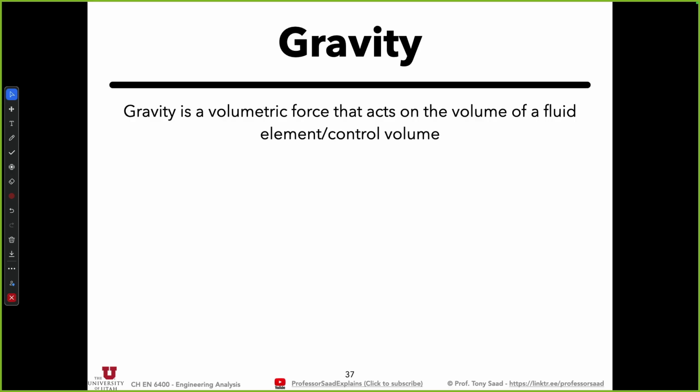Or you could be moving in a truck and accelerating, and the fluid is going to be accelerated, like a truck transporting gasoline, for example. As it accelerates and slows down, it's like there is a gravitational force pulling on the liquid, right? It moves back, and then as you slow down, it's going to slosh forward. So there could be acceleration fields in all different directions. We'll consider gravity, or any other acceleration field, as being three-dimensional. There's a gravitational component in X, in Y, and in Z. Typically, we take the Z direction to be the vertical direction, and that gives you Earth's gravitational acceleration.